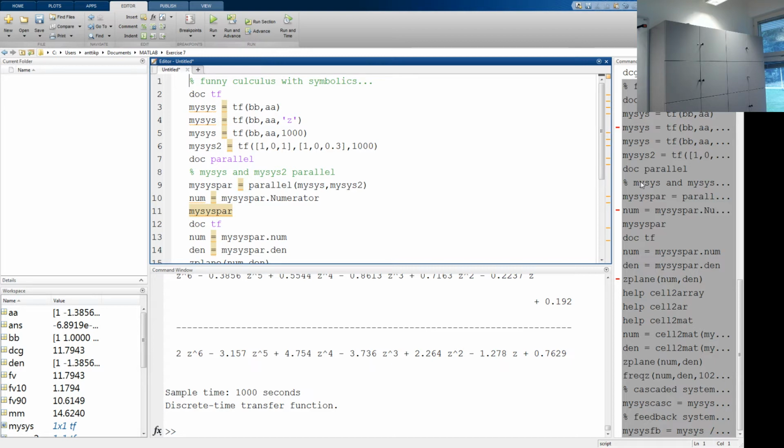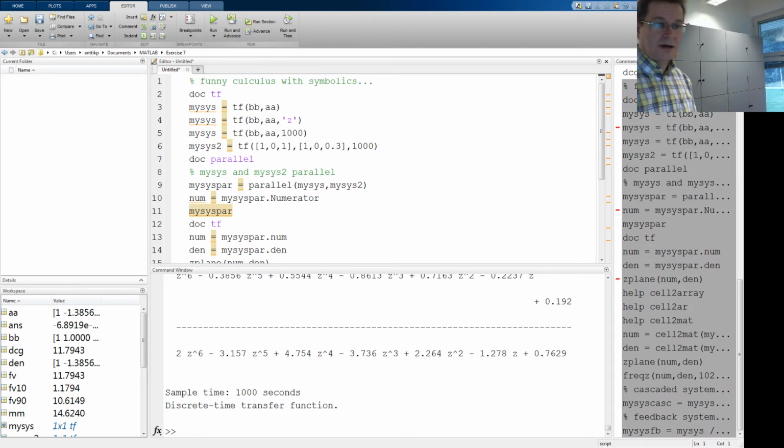Maybe. But fiddle with the P, I, and D values one by one, so that you get, as I asked, better rise time, better settling time, and smaller overshoot. I'm not telling how much better. You can define it yourself.